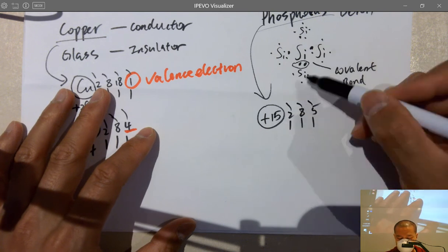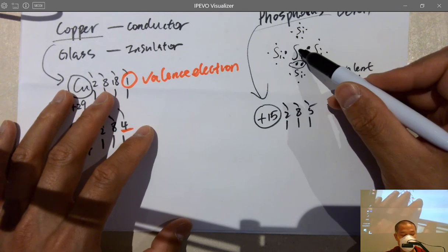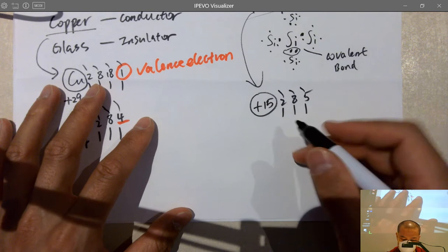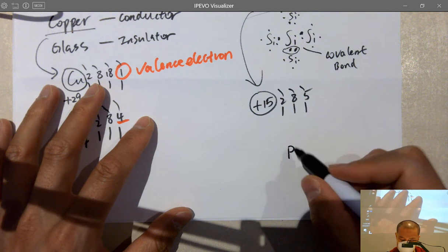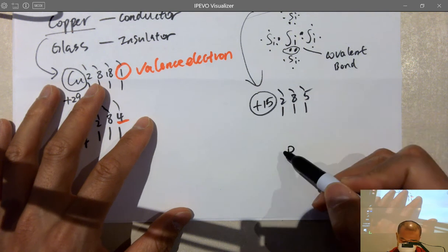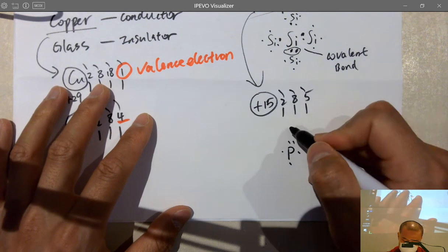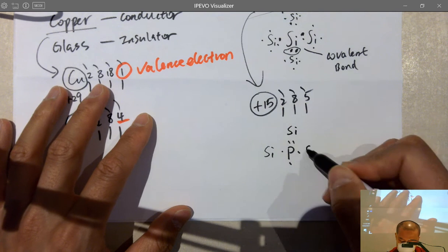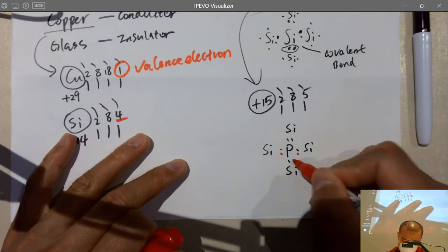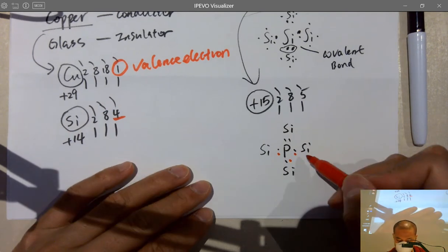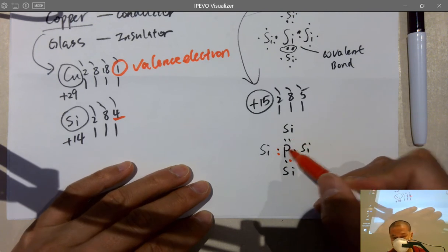The way that it's mixed with all the silicon atoms is it just replaces one of the silicon atoms, for example, one phosphorus atom, with a P in here, but 5 free electrons, like that. And then it still has a lot of silicon atoms around it, but only 3 are able to form these covalent bonds, but this one has been occupied by this phosphorus electron.